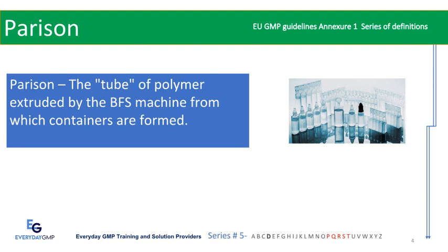In general, there are 3 main types of blow molding: extrusion blow molding, injection blow molding, and injection stretch blow molding. The blow molding process begins with softening plastic by heating a preform or parison. The parison is a tube-like piece of plastic with a hole in one end through which compressed air can enter.